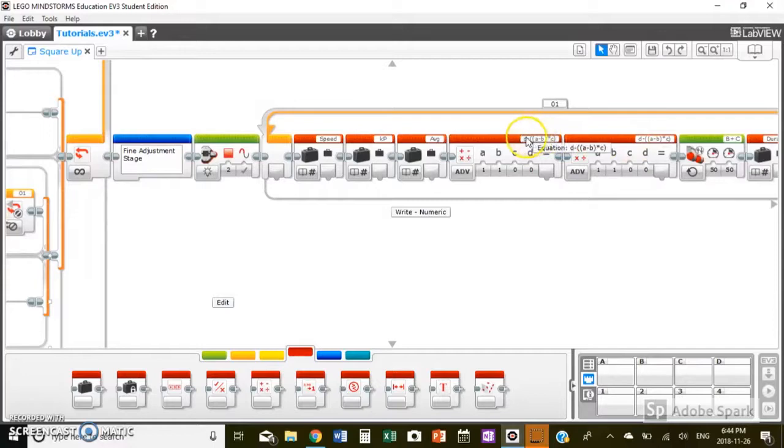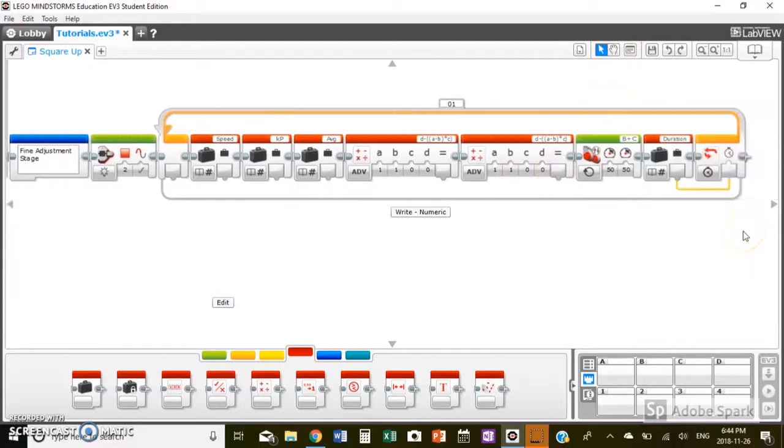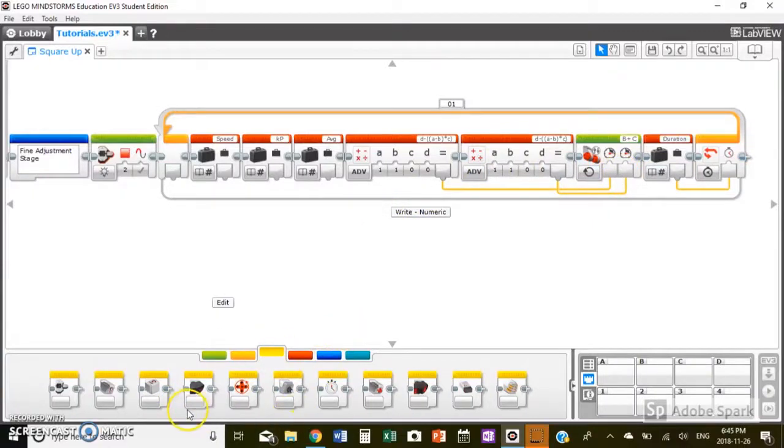It actually is minus and minus, or plus for both of them, and that's because unlike a line follower where we'd be making corrections in the horizontal direction, we're making corrections in the vertical direction here, and we want to have each of the light sensors control the motors independently. If you don't understand what I mean, that's fine. I'll be more thorough about that in a future video. Anyway, we plug each of these into their respective math blocks, their respective motor powers.